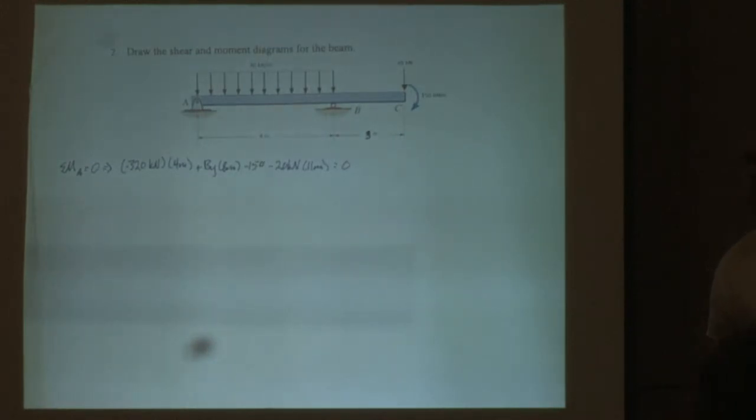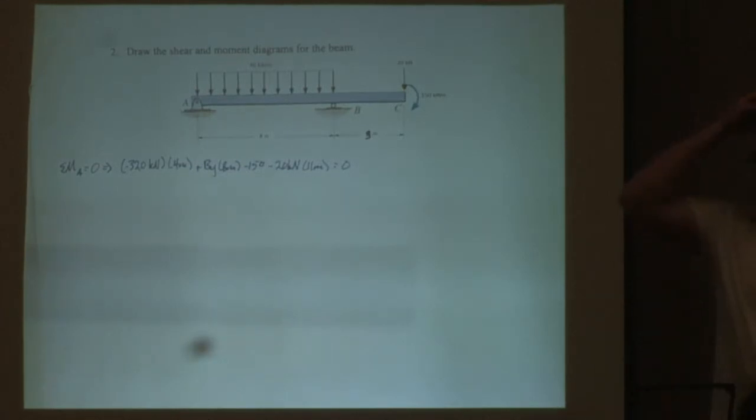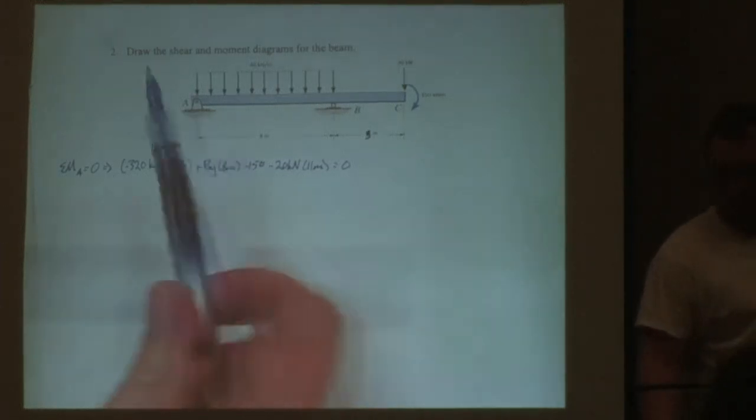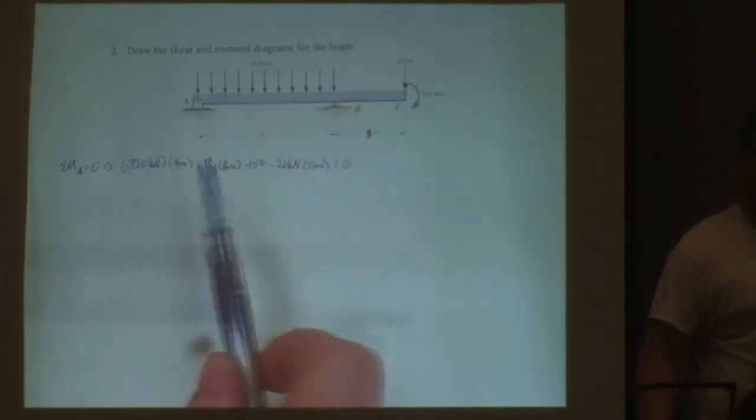Okay. So yeah, I took the base times height of the concentrated load, got it into a single force, put it down the center.